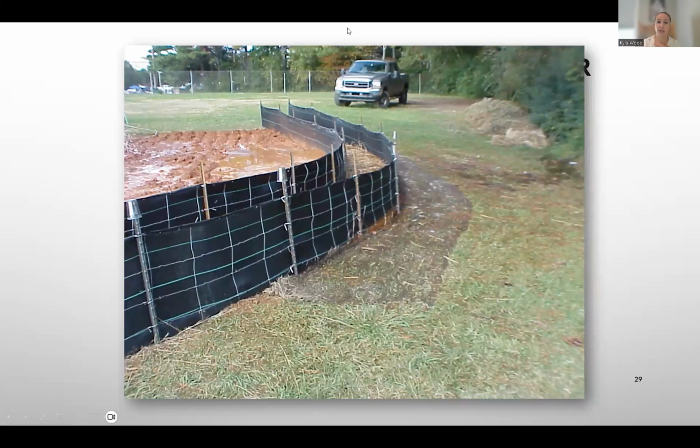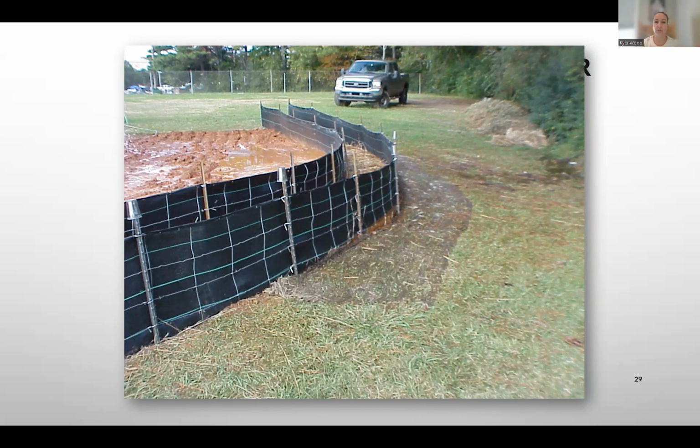You can see we have this slow moving flow of water. I'm going to see if I have the front side picture. I don't. So we have this slow moving, high turbidity water on the left side of the silt fence. It moves through, reacts with the granular polymer, and starts collecting on the straw in between. Then at the final row of silt fence, you can see there's some sediment collecting at the base. So that silt fence is still collecting some of that flocculated particulate. They did put a little bit more jute matting down along the backside as a final line of defense, and then we have our clear water flowing off. So it's a great way to enhance a silt fence and turn it into a water clarifying device.